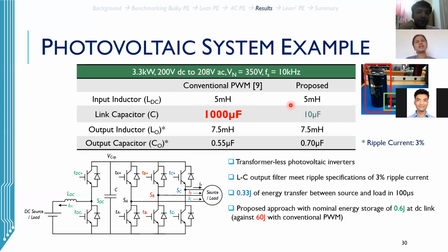One of the reasons that we wanted to do that was to show that, even though the conventional thinking, which is true, is that when we increase the switching frequency, we can reduce the size of the energy storage elements, even with a small switching frequency operation, we can reduce the value of the capacitor. But definitely the switching frequency is not a limit in this situation. Understood.